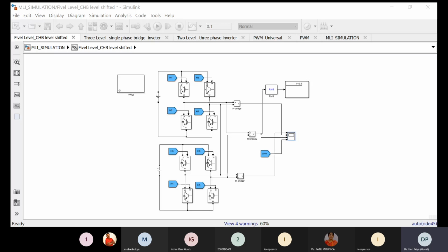You can see the slide of the T-type. This T-type is one of the simplified configurations. This is also responsible for 5 level. This is an overall 3-phase structure; let us see only one phase. In each phase they are using 1, 2, 3, 4, 5, 6 switches. So how many levels can it produce? According to this condition, if I turn on S1 and S4,